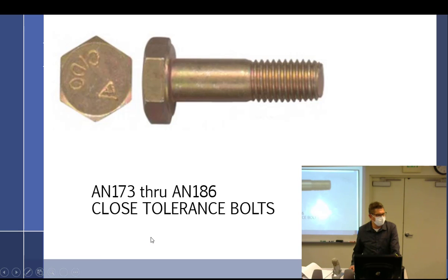Like, you don't want the threads to stick out too much? Well, you can't. If the threads stick out, well, okay. You don't want the thread to stick out too much because you're only allowed to use an 1/8 inch worth of washers. There's a minimum. I say 4, but I've seen some things say 4 and some things say 1/8 inch. But if you're using 4 washers, you got the wrong bolt. If you've exceeded 1/8 inch of washers, get the next bolt size down, which is 1/8 of an inch less.